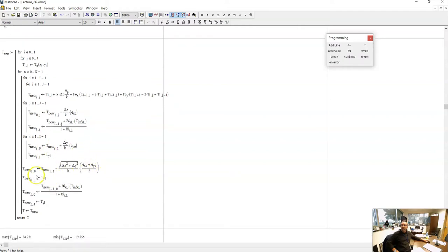And then for the corners, at 0, 0, remember, I would impose an average of the two fluxes, qx0 plus qy0, which will end up being 0 because these two will cancel each other. In this particular case, one is heating and one is cooling at the same rate.